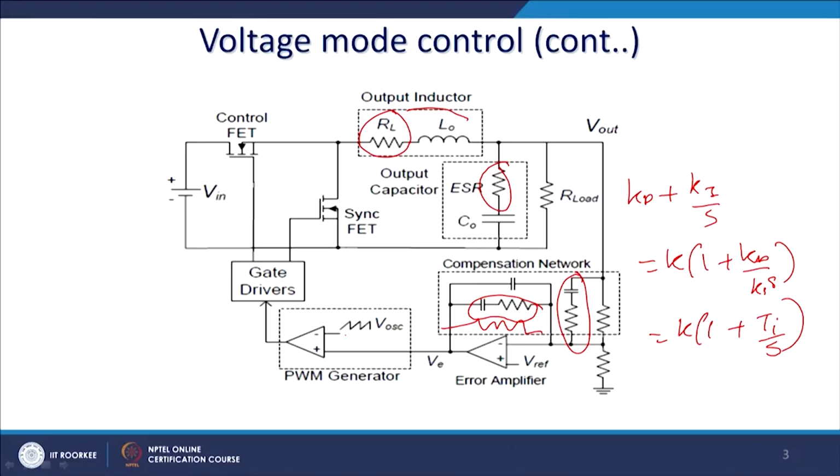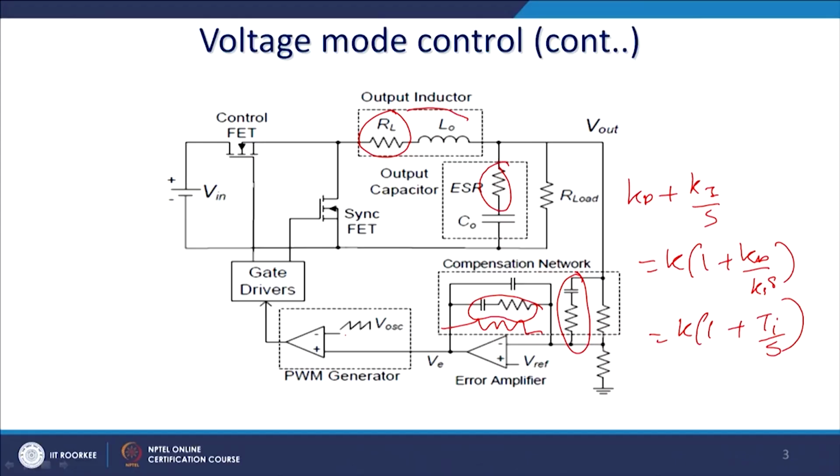To reduce the losses, since when the MOSFET is on, it is only RDS on, losses will be very much minimized. For this reason we use a synchronous buck converter nowadays instead of the normal buck converter, and this is the way it works. What is the disadvantage of it? Definitely it is not short circuit protection free.